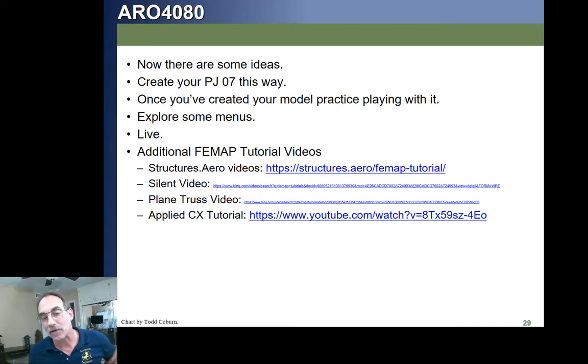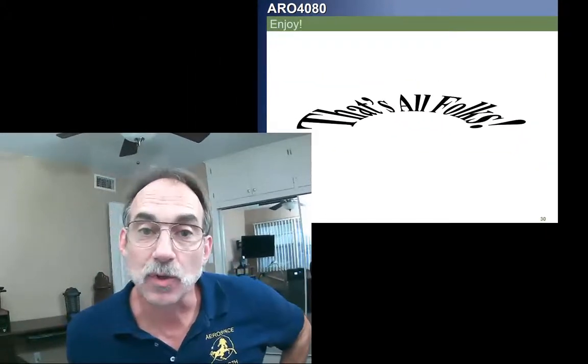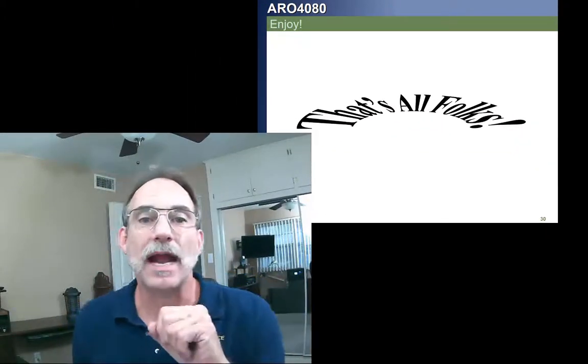Many of the tutorials out there are going to teach you to make things that look really complicated really fast. And as you probably have sensed, I'm going to recommend keeping it simple. That doesn't mean it's not valuable to make some of those models. If you've got a tutorial, go ahead and follow what they're doing and see what it is. But I want you to become suspicious of anything that creates a lot of output. The higher elements, the more complicated elements, mostly bring back a lot of output that it's very difficult to decipher what it actually means or if there's an error. So this is just to get you started. That is a quick tutorial for FEMAP. Go in there, practice, and enjoy.